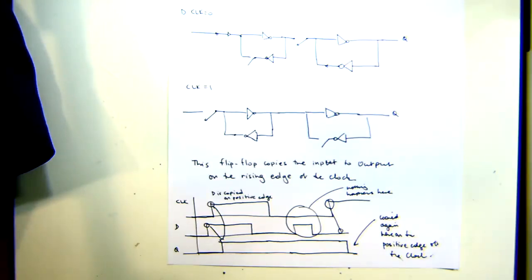And what that allows us to do is to say, well, if we make those circuits small enough and we've got a little bit of flexibility with the clock, we can start trying to design these circuits so that, given the propagation delay, the asynchronous circuit processes the input signal so we get an output at the input of the flip-flop, so that when the clock arrives we sample it and we know that we have a known good stable signal. Okay,